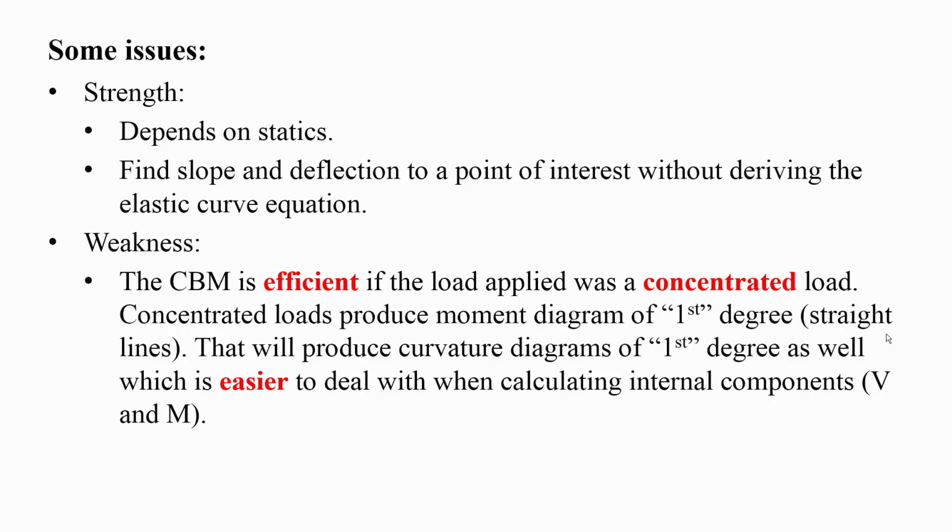And here's why. Concentrated loads produce a moment diagram of the first degree, straight lines I mean. And of course, if you divide the moment diagram by EI, the curvature diagram is still of the first degree. And if you take this curvature diagram and apply it on the conjugate beam and try to take a cut and find the resultant forces produced by a segment of a load, it's easier to calculate the area under the graph to concentrate the load, just like I did with the triangular loads. But let's see a simple case where it's a little bit inconvenient. We can get to the solution using the method, but it's not as straightforward as it used to be.